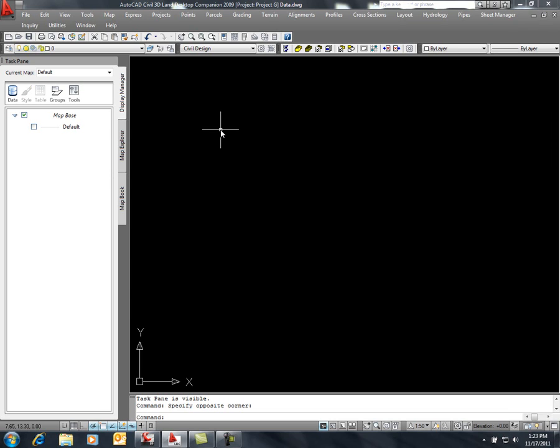Now in this particular situation I need to construct a surface. I also need to start generating some pipe runs, and the originating data that I have given to me is 2 shape files. So from a Land Desktop perspective, there's not a lot that I can do. I might be able to view those files as geospatial entities through FDO or through the task pane. I may also be able to import them as shape files and then try and build a surface from contours, but I can certainly facilitate or work with that data much faster using Civil 3D.